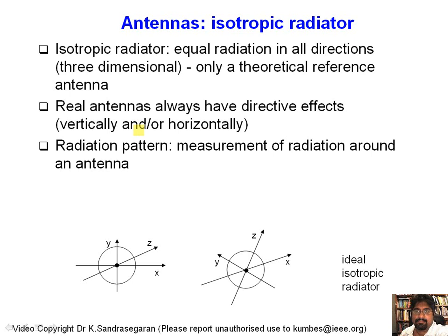If you look in the specifications of this antenna, it has antenna type, frequency, the impedance, the connector that you use, and what is the maximum power it will radiate. So this one has 10 watts, and then it has a gain, and the gain of that omnidirectional antenna says 8 dBi. The I there refers to an isotropic antenna, with respect to an isotropic antenna.